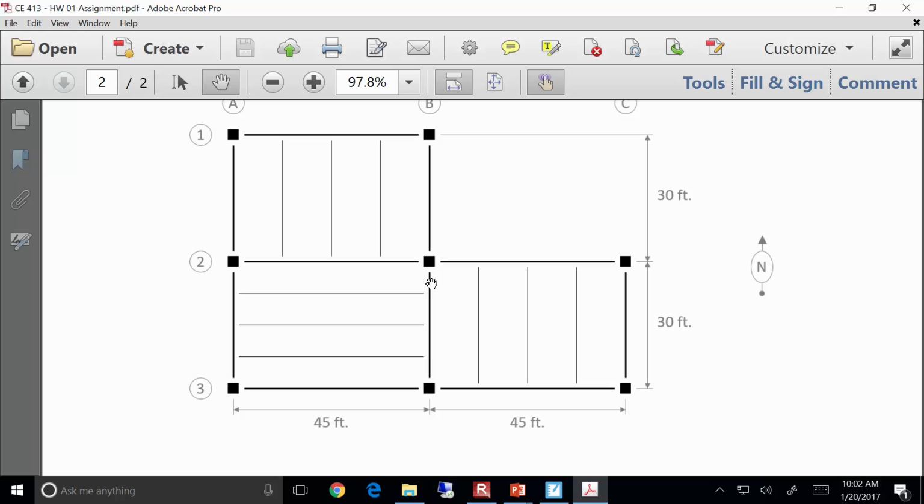Okay, all right, so here's what I'll say about the girder. So we're talking about determining the response on this element right here, right? Okay, all right. What I'll say about that is this. Remember, when you've got girders, you're not going to be taking a pressure load and turning it into a uniformly distributed load. You're going to take, remember, the hip bone connected to the leg bone, those reactions distributed over, right? Okay, now, remember what we did on our example problem. We got the reaction on each floor beam, but then we said, we'll take that and multiply it times 2, and that'll be the point load. You remember that? Is that going to be the case here?